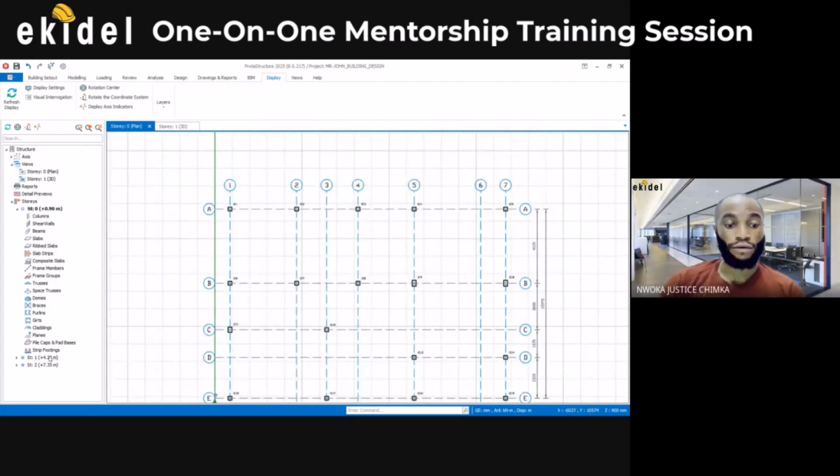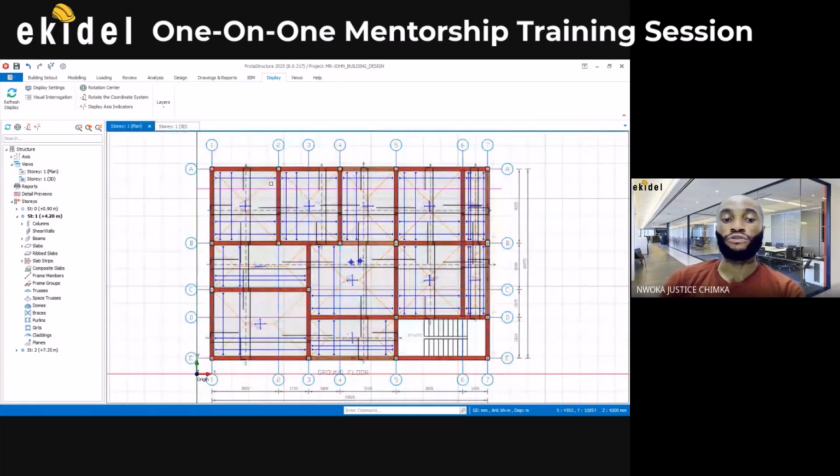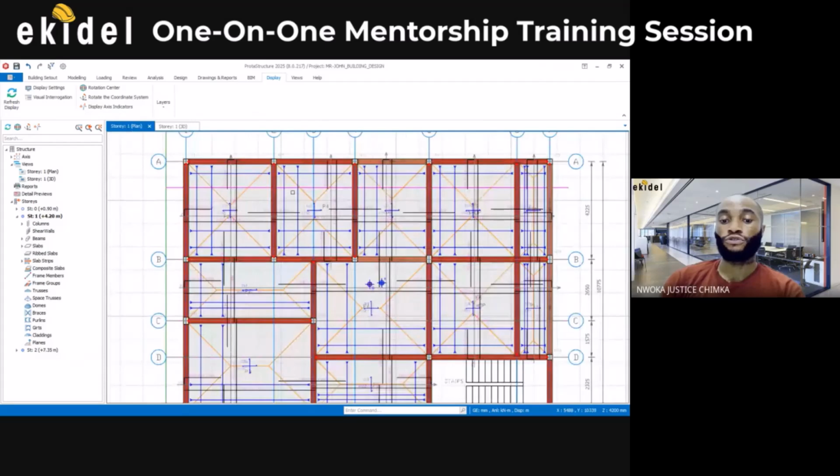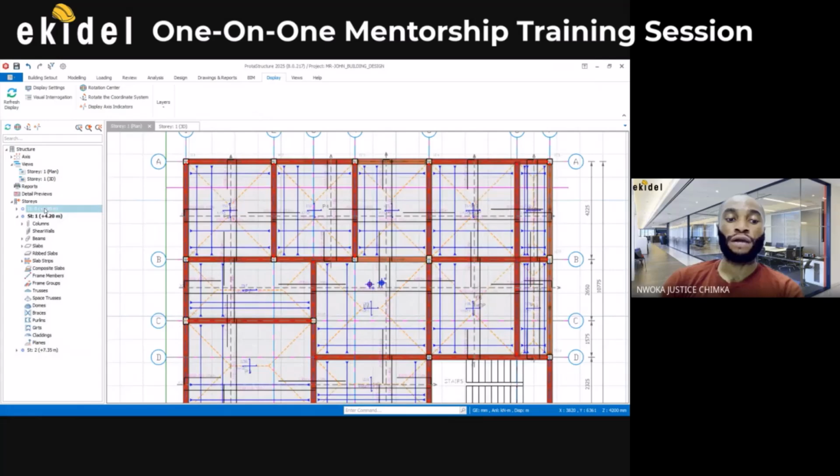Right now we are on story 1, the first story, and we want to begin the foundation design. Come to story 0 here and double click on it. While I'm on story 1, I'll click on story 0, then right click and you see select story. I'll now select the story.